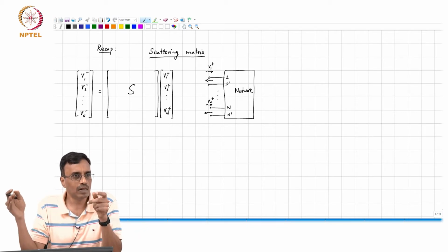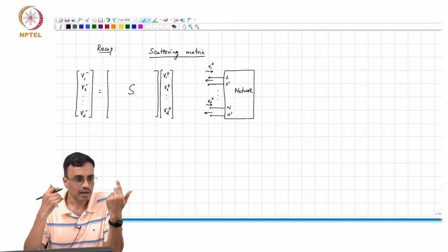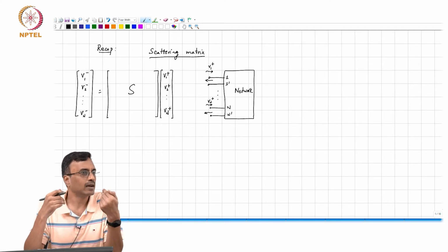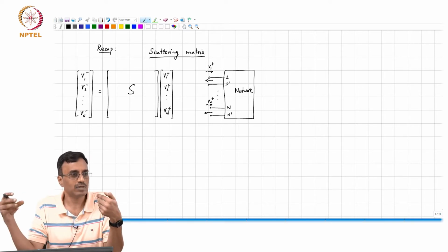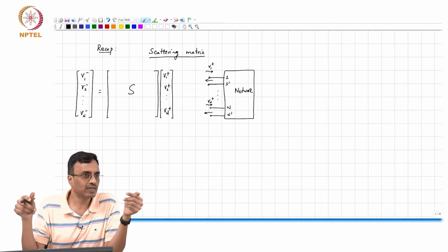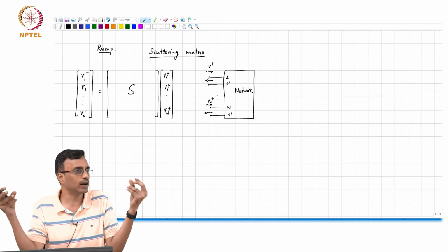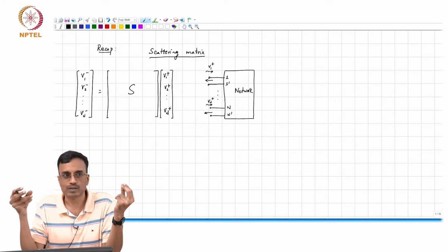So, the way around it is to avoid the root cause. As you can see, even though we terminate the cable or the transmission line with an open or a short circuit, at the other end it can look like something completely different. The only way to get around this problem is that we need to terminate the transmission line in some magic impedance, and when you look at the impedance on the other side of the transmission line, what you want is that the impedance should be independent of the length of the transmission line, right?